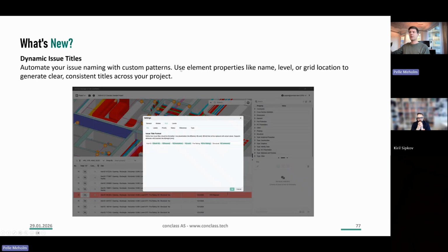The last main feature I want to name here is the dynamic issues. We already have the possibility in Revit to define issue titles based on a specific pattern. The pattern allows you to define a rule on how to write or describe a title based on parameters. Based on the structure, Convoid will extract the parameter values and replace these placeholders to allow a standardized issue title.